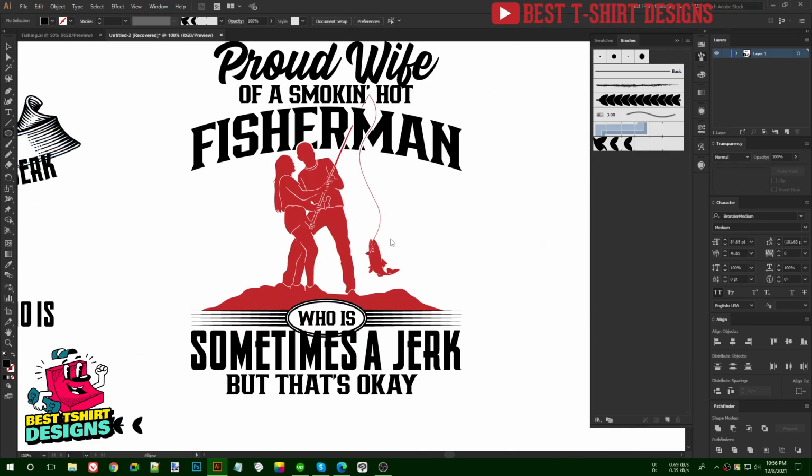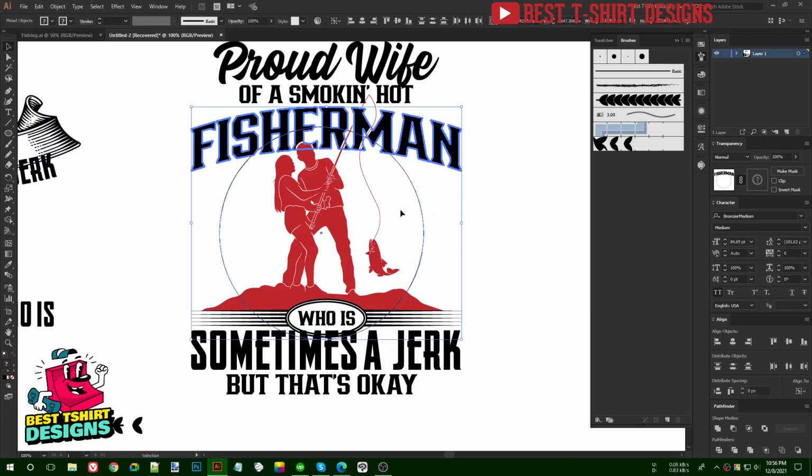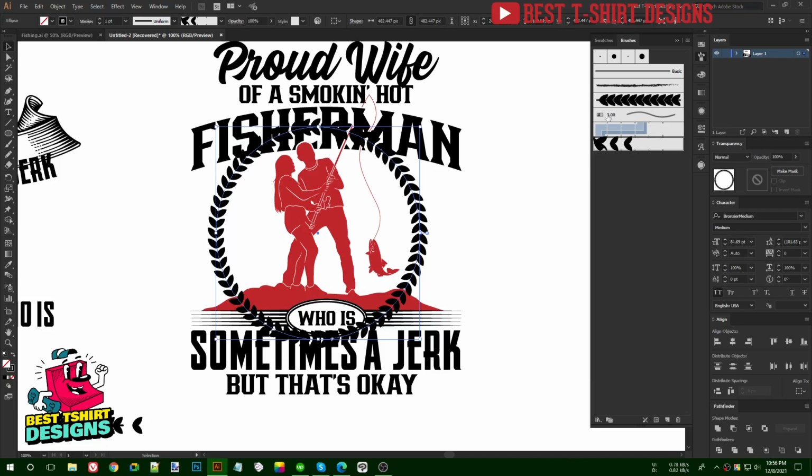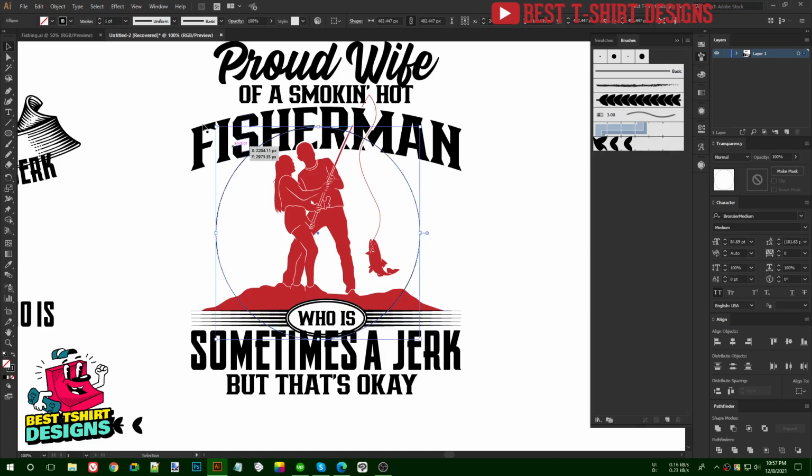Now for the center position here, I will create an ellipse like this. Now I want to place that in the center position with our main graphic. So I can simply click on this pattern brush, and this is how it is looking, or I can click on this art brush. The problem is the art brush fits the entire area with one single shape. You can see this shape is stretching and filling all the area, but the pattern brush creates a duplicate copy each time, and it feels like this. So this is also good, but for now I will just use a simple shape.